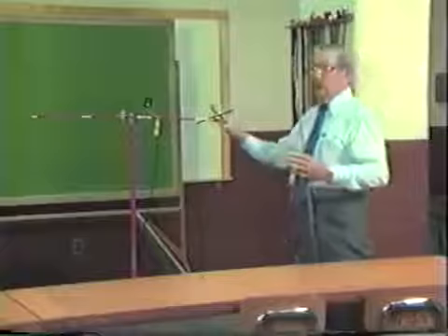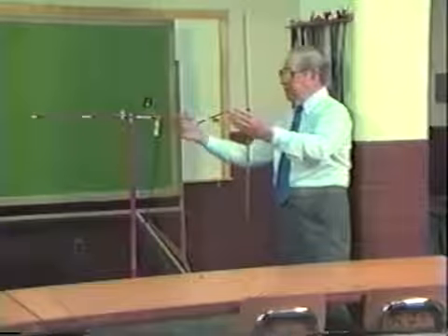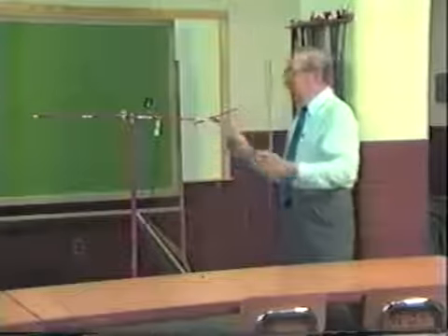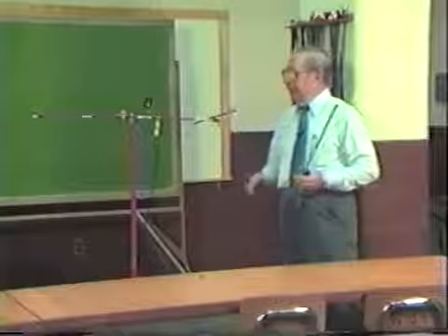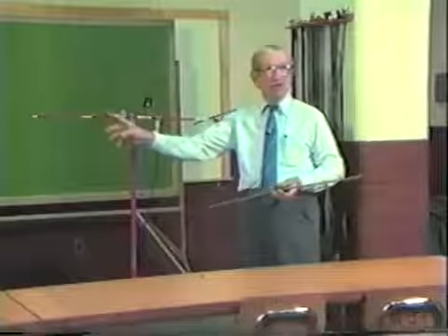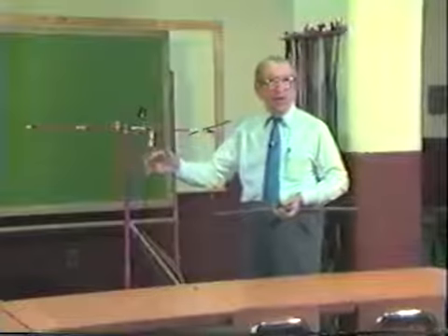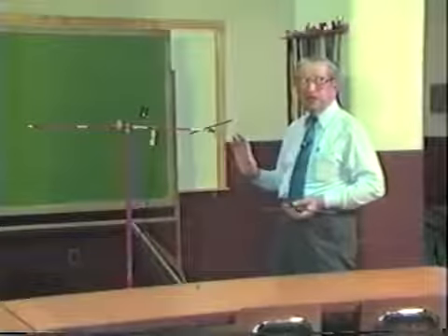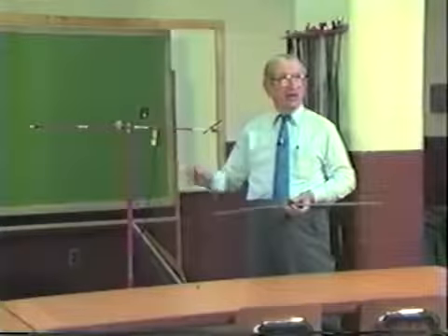As soon as we put a reflector behind that driven element that's 5% longer and spaced a reasonable amount behind it, it forces the signal to go in that forward direction. By the same token, the directors, being 5% shorter, will take less time for the RF to build up on them, and it causes a reaction, a phased effect that forces the signal into that forward direction.